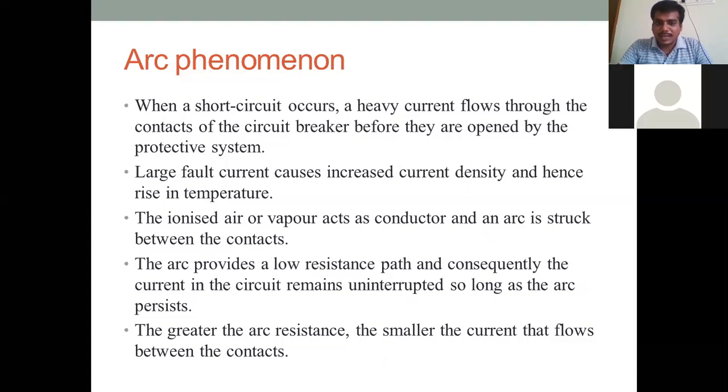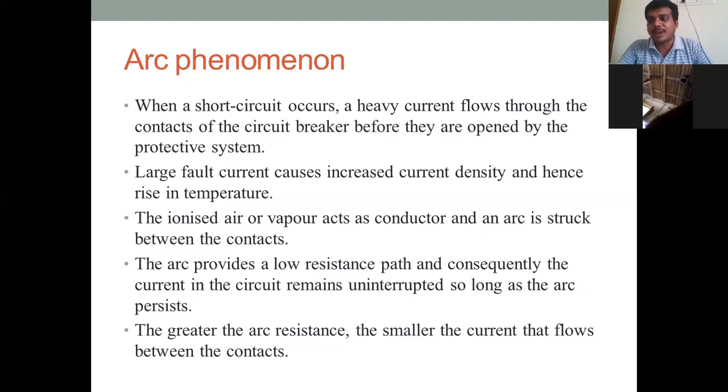So therefore the current in the circuit will be uninterrupted as long as the arc is continuing. So the greater the arc resistance, if you are maintaining the greater arc resistance, the current between the contacts will be very small. So this is the technique which we are going to implement for reducing the arc.